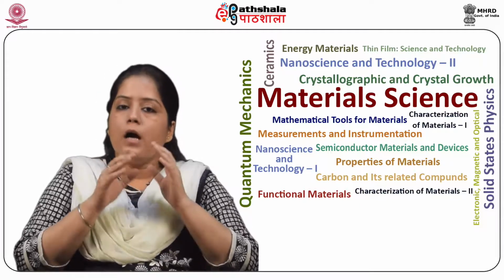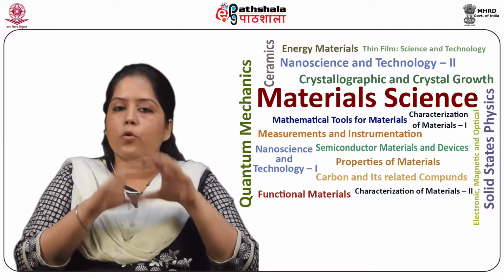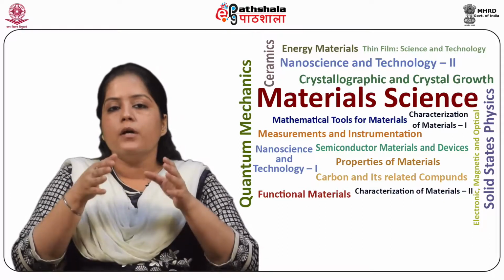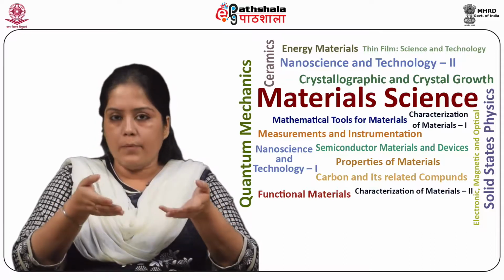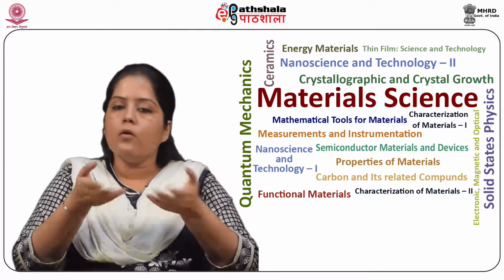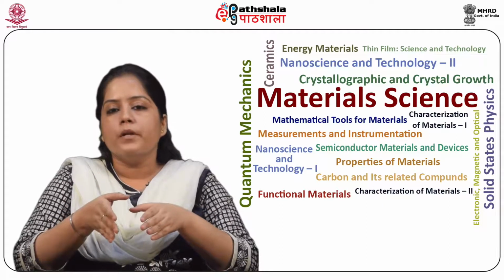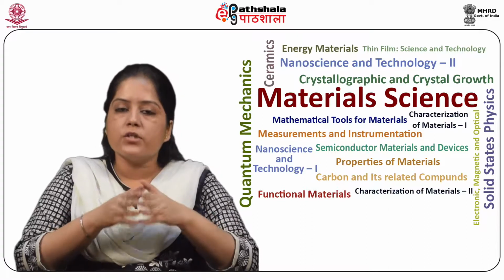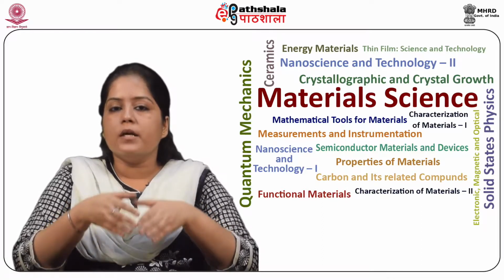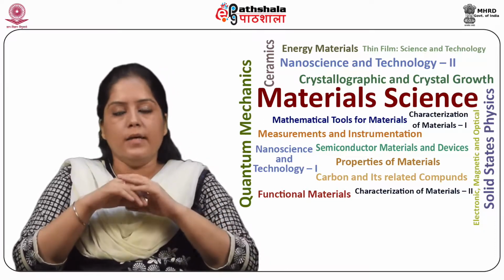The development of superalloys depends on both chemical and process innovations. For example, the high temperature strength of superalloys stems from both solid solution strengthening as well as the precipitation of matching phases like gamma prime. Many times oxide strengthened alloys are also used. Elements like aluminium and chromium provide corrosion and oxidation resistance. Superalloys find application in making turbine blades and engines used in both aerospace and marine.